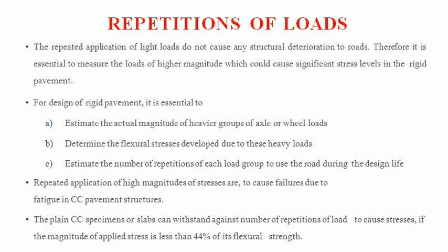So for the design of the rigid pavement, it is essential first to estimate the actual magnitude of the heavier groups of axle or wheel loads. Second, to determine the flexural stress developed due to these heavy loads. And thirdly, to estimate the number of repetitions of each load group using the road during the design life.